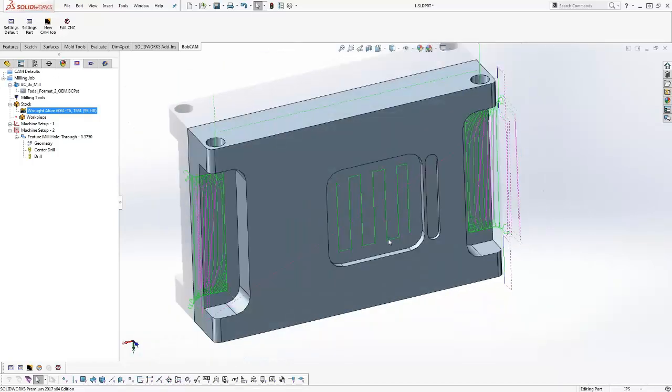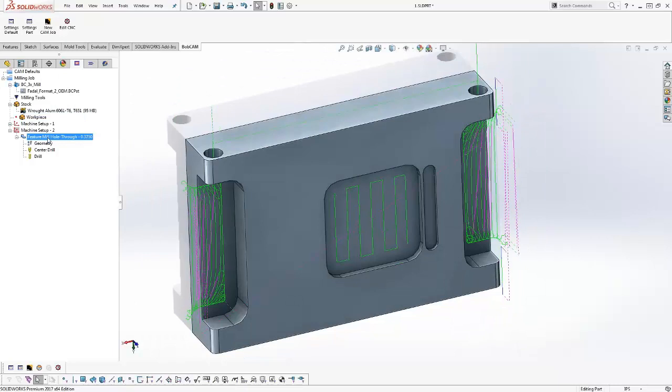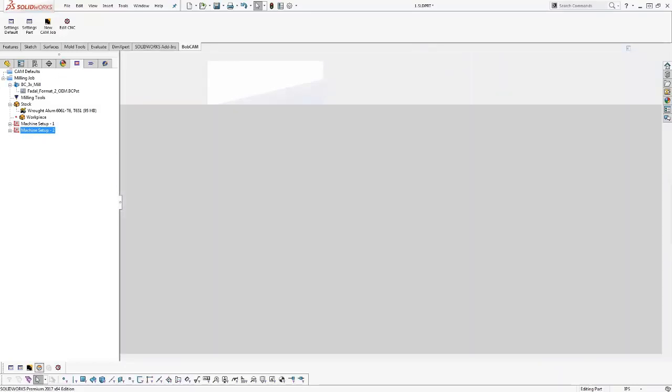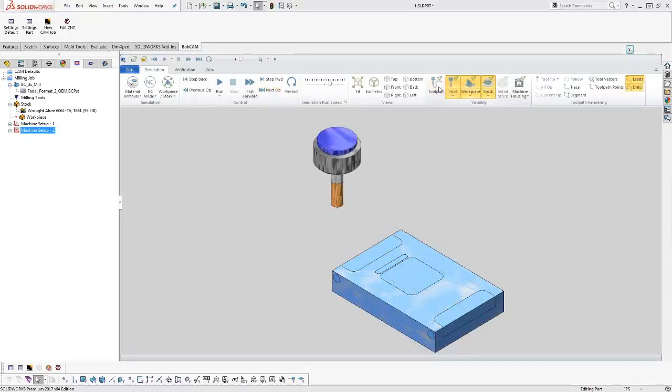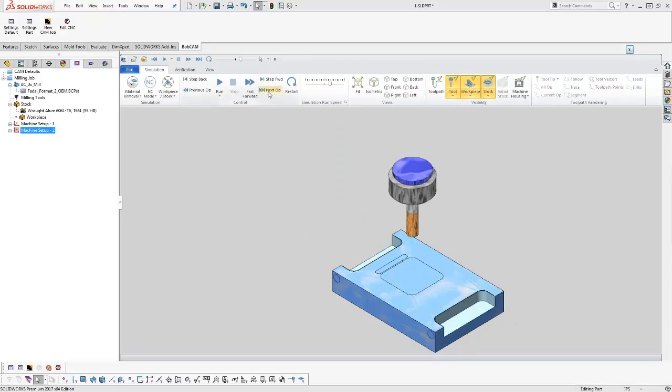Now, we did this, we drilled and tapped on this section over here. Now what happens when you have two different setups within the simulation? Like what happens in simulation when you have 2 or 3 different part flips or whatever the case might be? The software will just pick up where the flip is. So we can go next stop. Let me turn the toolpath off. So we can go next stop, so that one does that. We go next stop, that one does that.